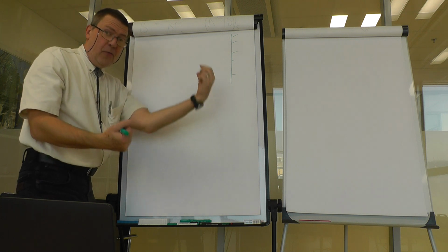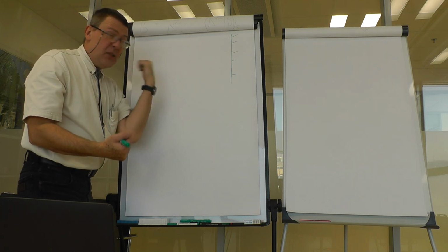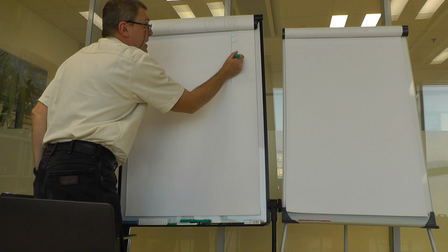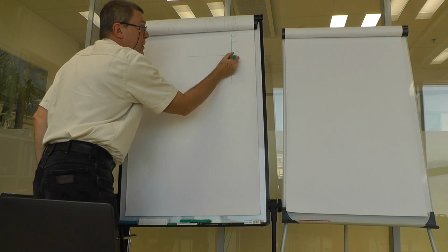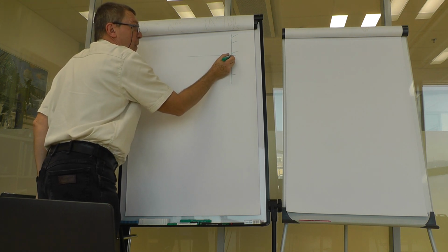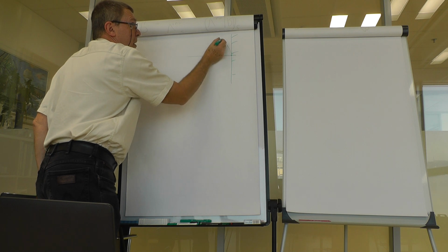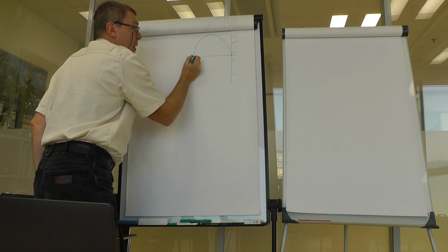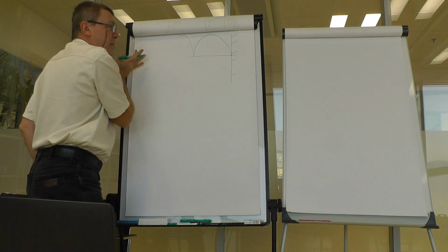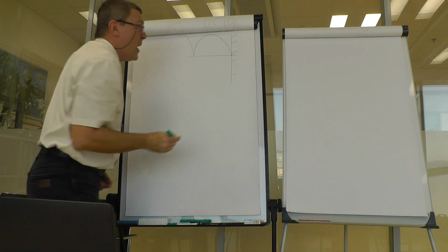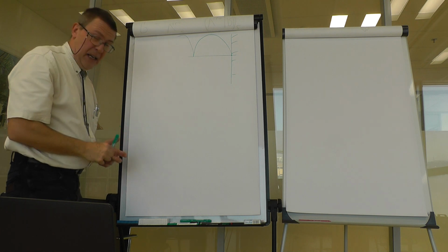The whole power reflects back. At the interface there is zero voltage or zero field strength. And we have a perfect standing wave ratio in the part from where the wave has been coming.